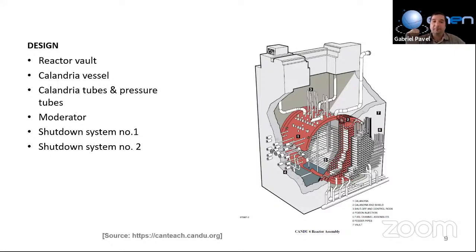Now, this huge pipe is housing smaller pipes, which are called calandria tubes. Inside these calandria tubes, which are placed in the moderator functioning at very low parameters, you can find the pressure tubes. As they bear the name, the pressure tubes are the tubes that support most of the efforts, both in terms of pressure and temperature. So inside the pressure tubes, we have increased pressure, increased temperature, increased parameters.